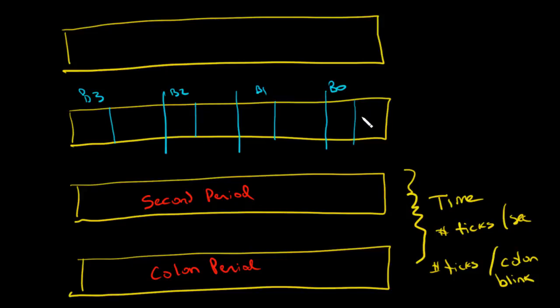And for instance, this could be digit 0, and this could be digit 1, digit 2, and digit 3. And in this mode, the blue mode here, will be my BCD display. And so when you think back to what we've done before, I would take these 4 wires and connect them into the BCD display for digit 0. And those 4 wires go out to digit 1, and those 4 wires go to digit 2, and those 4 wires go to digit 3.